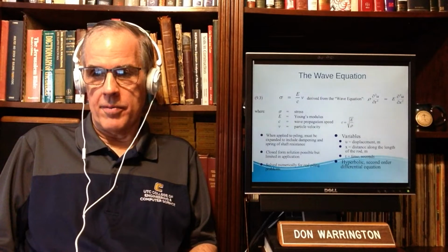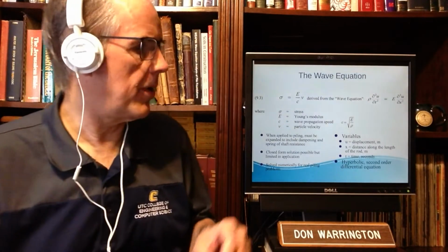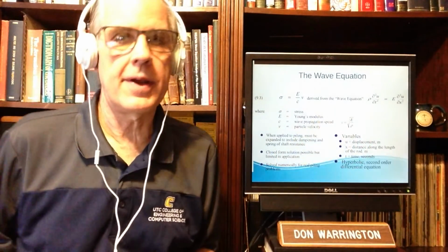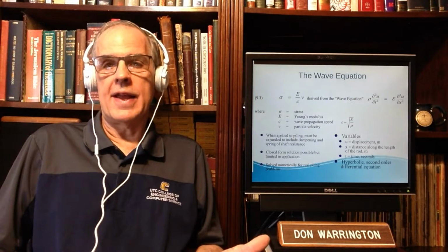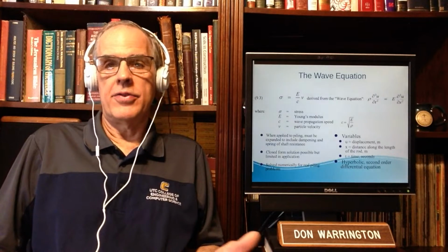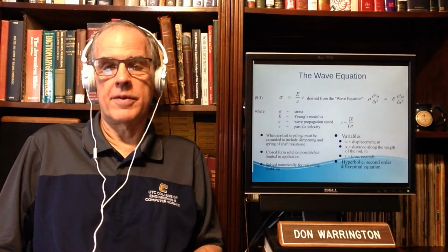So the key, though, and both of them discovered, is right here. This is the acoustic speed in a pile, or in any elastic material for that matter. This equation finds a lot of use in ultrasonic testing techniques.